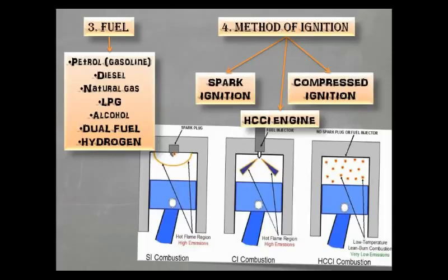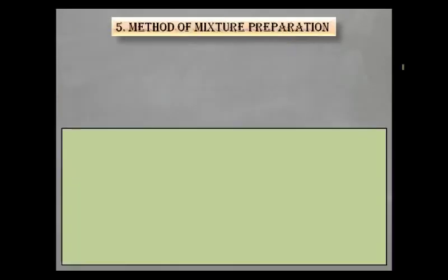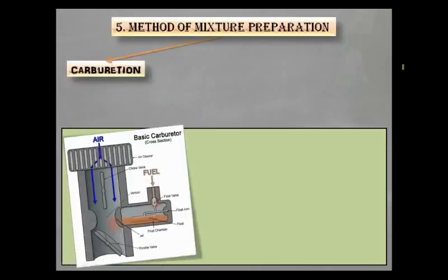During the end of compression stroke, ignition occurs through self-ignition in the whole combustion chamber at once, that is instantaneously. Since the mixture used is lean, the maximum temperature both locally and overall becomes low compared to other engines, which effectively reduces the NOx formations.